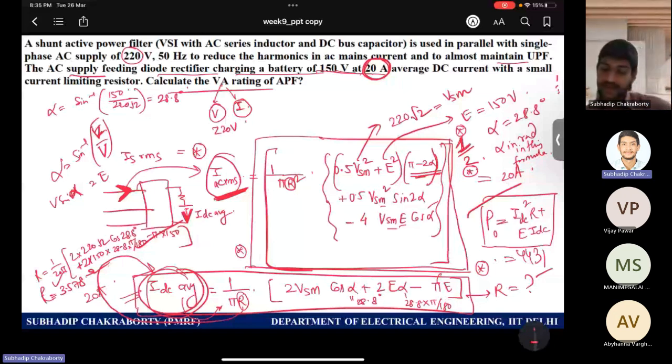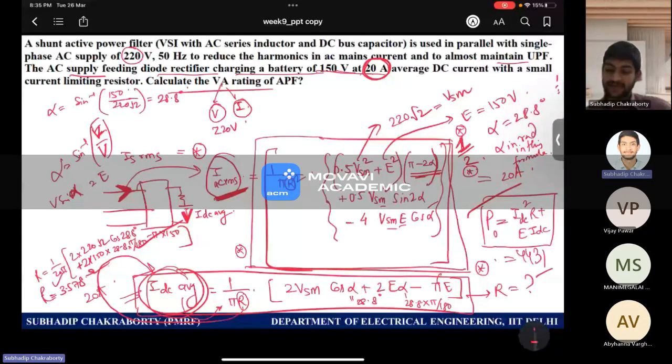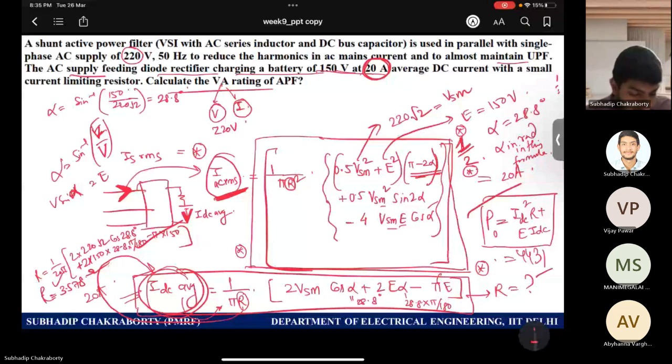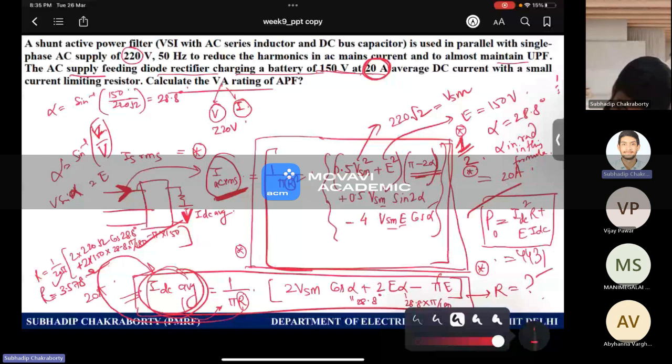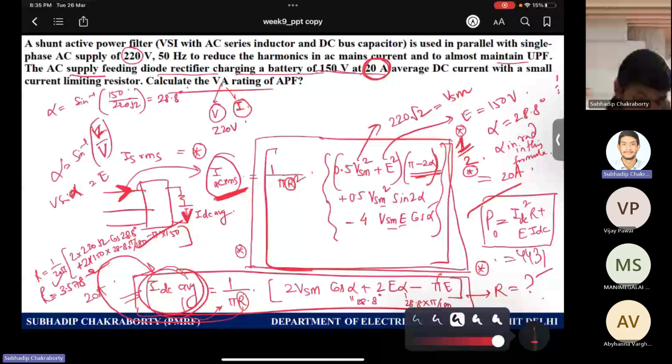So if you now know the active power, by power balance I can find out the fundamental of the supply. The net power is 4431, power divided by voltage, right? So voltage is what? 220 RMS. So I find IS RMS. It is 4431 divided by 220. Done?